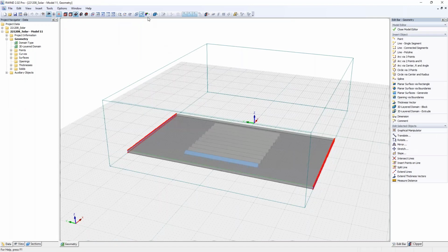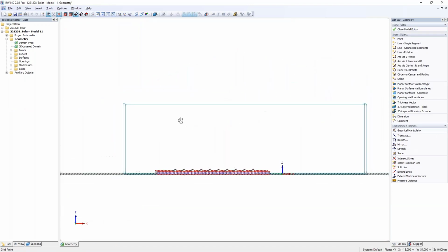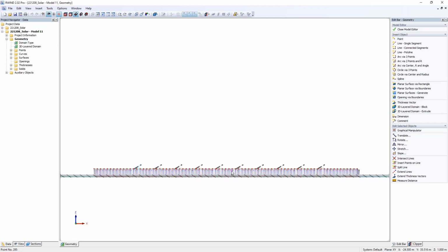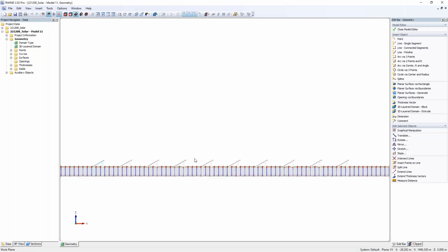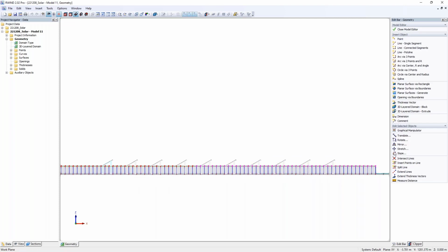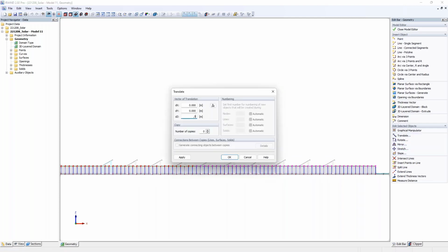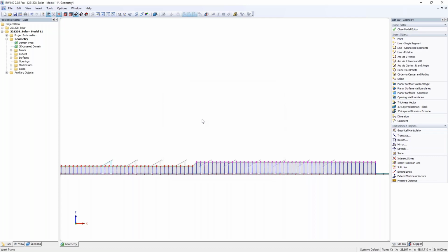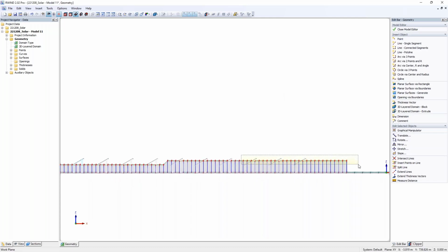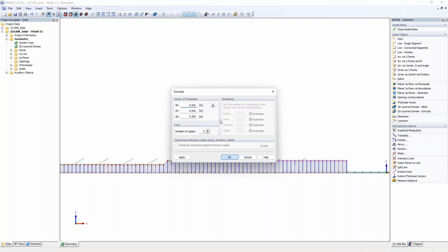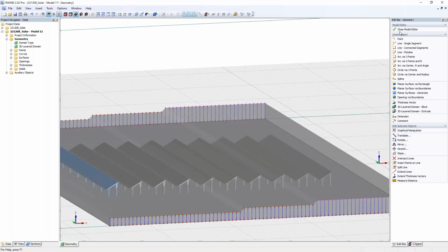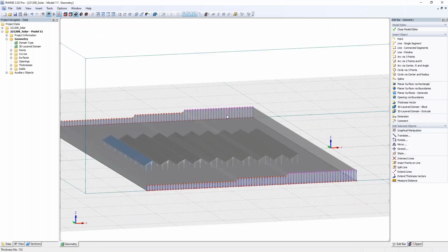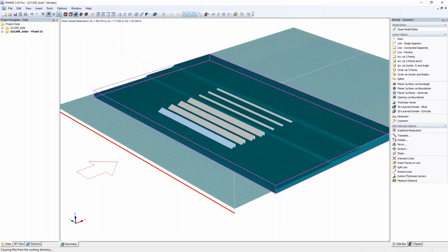And I hit OK. And then you can check from the side to see where the solar panels are standing. And in our example, I just want to raise a half of this terrain with the thickness vector to be moved half a meter to the top. Yeah, half a meter top. So if you enter it with a dot, then it's not giving you the warning. And the last three ones should also be moved half a meter to the top. So you can see with this terrain editor, you can just quickly arrange a staircase terrain, or if you have some other crazy shape, you can of course also use those thickness vectors. And I will save it.